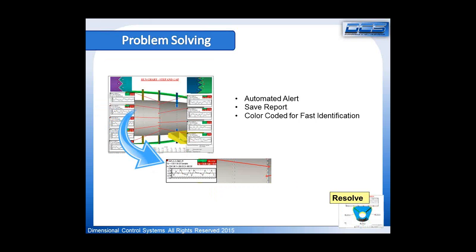So as you look at, for example, where there are variations occurring on individual parts that are being fabricated, being able to consider these in an assembly context long before you begin the assembly gives you a sense of what issues are going to occur, in this case from a step and gap perspective, in putting these skins together on the aircraft structure.